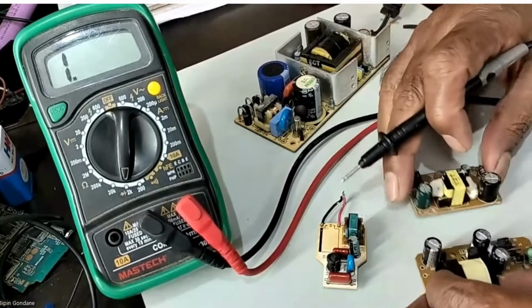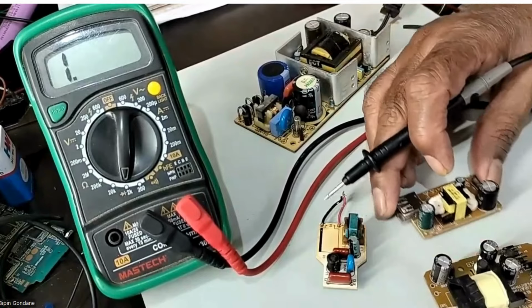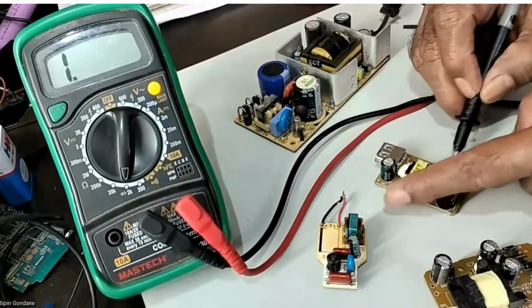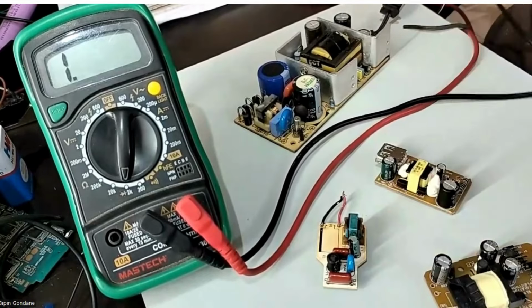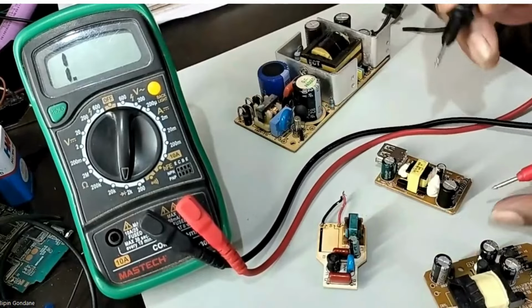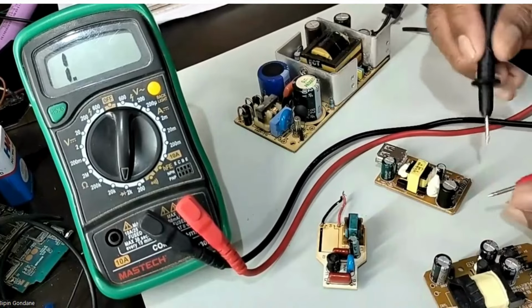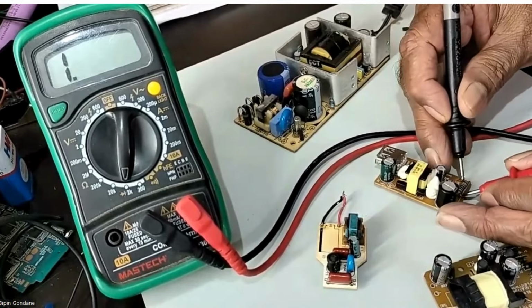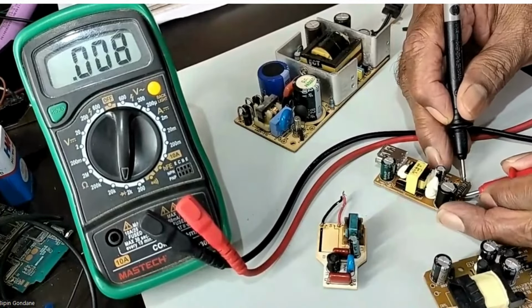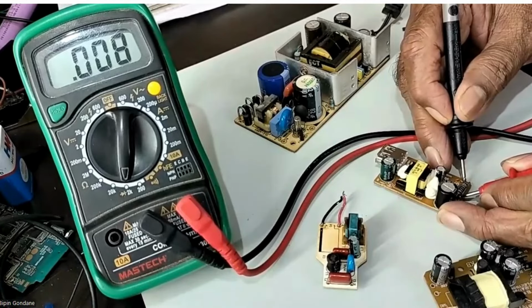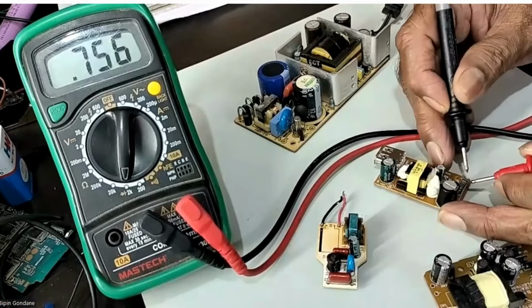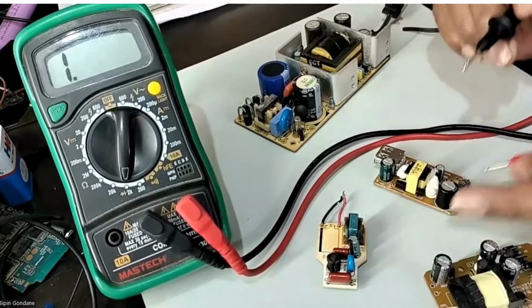In this case, a resistor is given at the two AC terminals, so you will check the resistor. How will you check it? You put the multimeter on the 2K range or 200 ohms range and check whether it's working or not. It is showing some resistance, approximately 8 or 10 ohms, that means the resistor is okay. The first part we have checked.